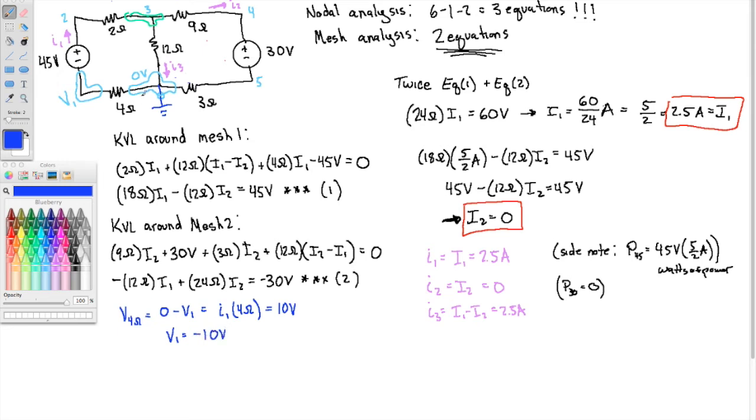You see, the current in a resistor always goes from high potential to low potential. The very first video, the marble rolls down the ramp. So I1 is going this way from right to left. So this is the higher potential. We're calling that 0. And what's the drop? Well, from Ohm's law, the drop is 10 volts. So if this is what we're calling 0 to be, then this must be minus 10.